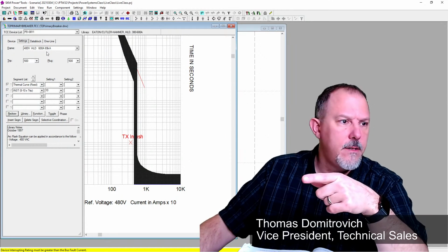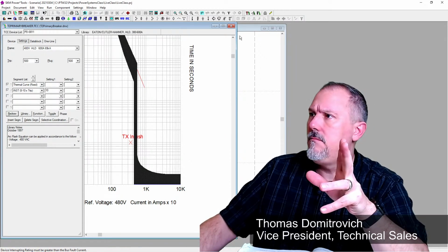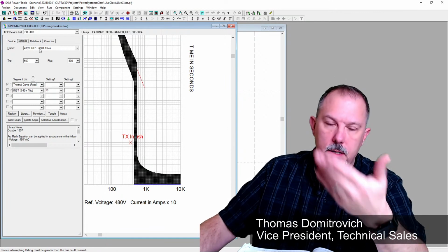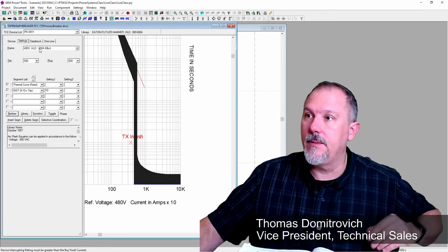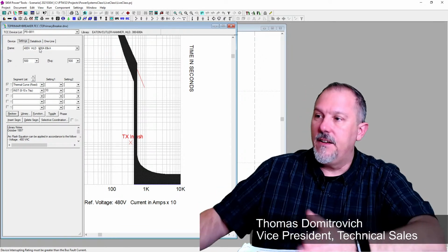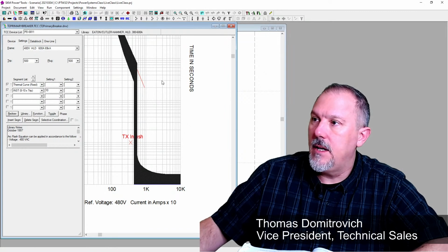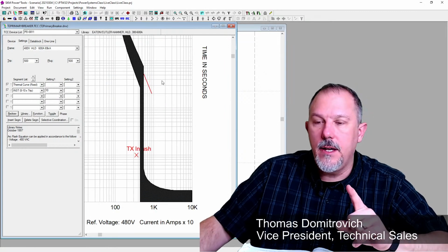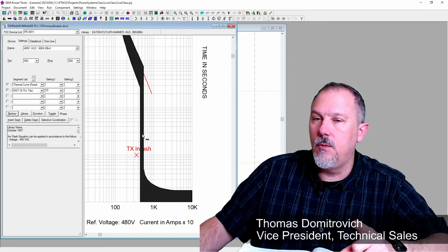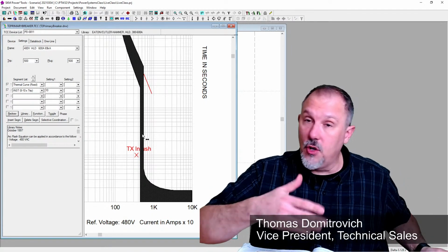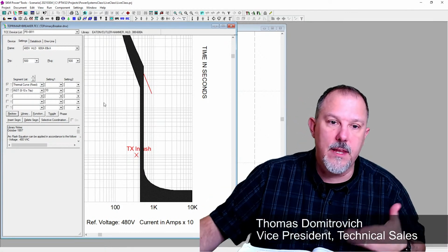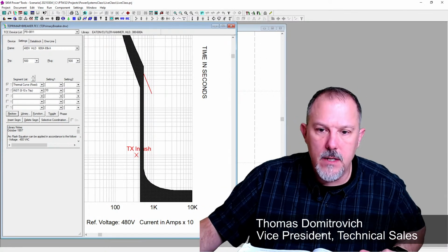For some reason where did I have 600 amps? Oh, it's a 600 amp frame, and it's at 500 amps. So it's a 500 amp breaker, and that was actually the recommendation from Eaton's perspective. You should always go back to the manufacturer and see what their inrush currents are and what they recommend and all that good stuff.